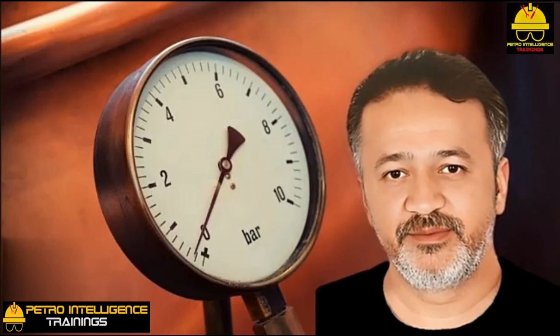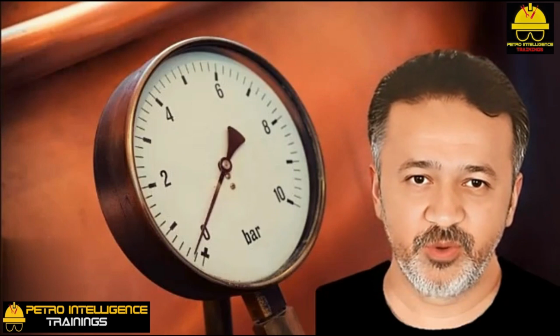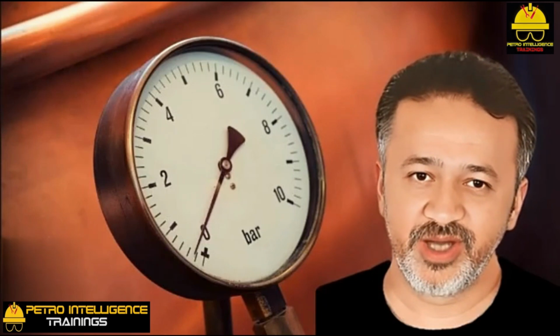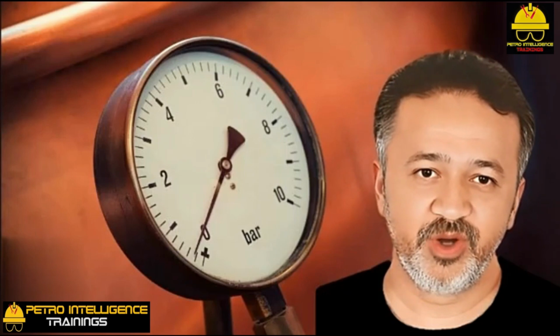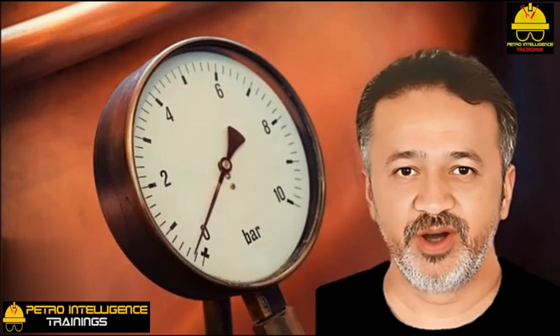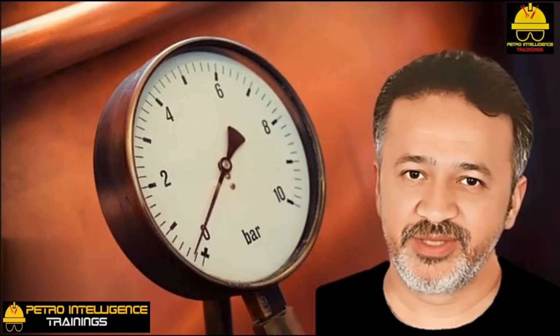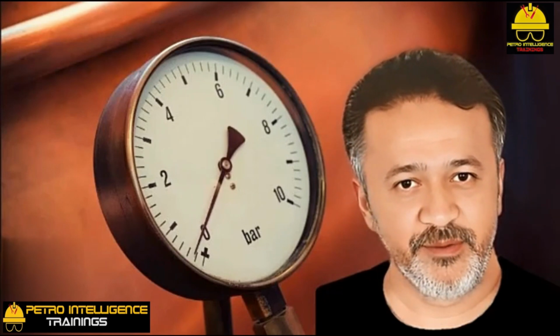It's wrong. The chief engineer failed to realize that the vacuum pressure indicator was not equipped with a barometric pressure compensator. An ordinary vacuum pressure indicator or pressure gauge reads the pressure difference between the vacuum system and atmospheric pressure. When ambient temperatures drop, the barometer rises, or ambient pressure goes up.